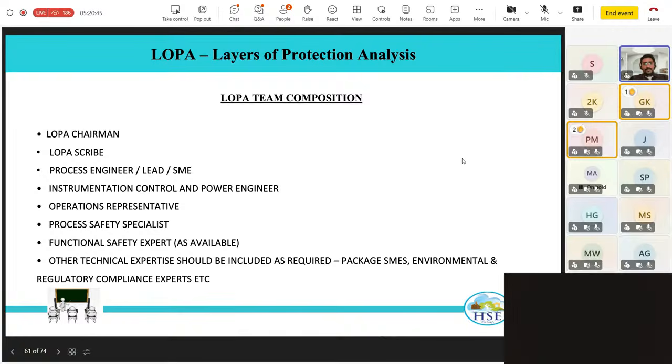Incidents happening aside, that is different. Not just for the gas blow-by case, even for PSV sizing. For gas blow-by, yes, when you are looking at the rupture of the downstream system, they consider it there. But even for normal PSV sizing, for the CV full open scenario, for calculating that they also consider both the main valve and the bypass valve. Next.